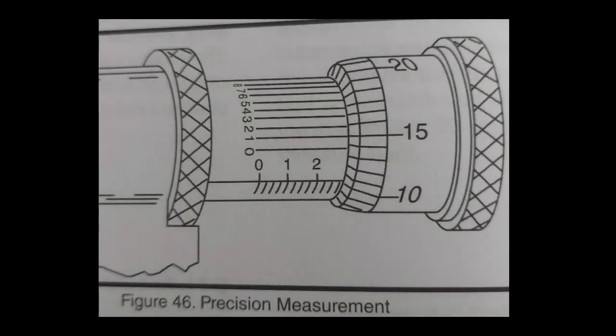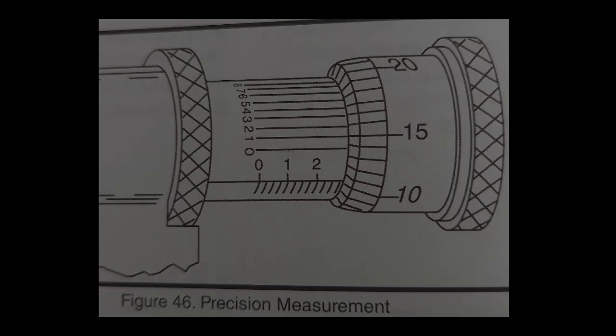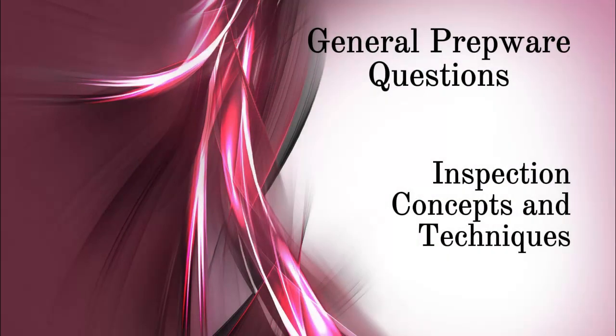Refer to Figure 46. The measurement reading on the illustrated micrometer is 0.2851. How can the dimensional inspection of a bearing and a rocker arm be accomplished? Telescopic gauge and micrometer. The 100-hour inspection required by federal aviation regulations for certain aircraft being operated for hire may be performed by appropriately rated mechanics and approved by them for return to service.